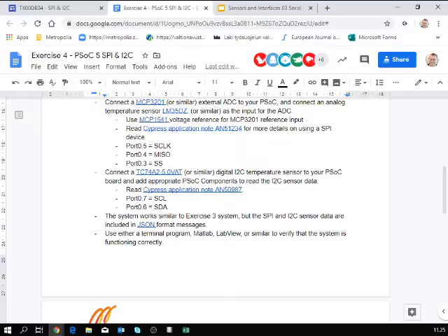Okay. Then another connection is the I2C temperature sensor. It's up to you which way to go, which temperature sensor you check first. Do not do everything at once. Make either the SPI bus first or the I2C bus first. But anyway, you connect that one. Port 07 is serial clock for that one, and port 06 is serial data. And okay, you also need those pull-up resistors for the I2C bus.